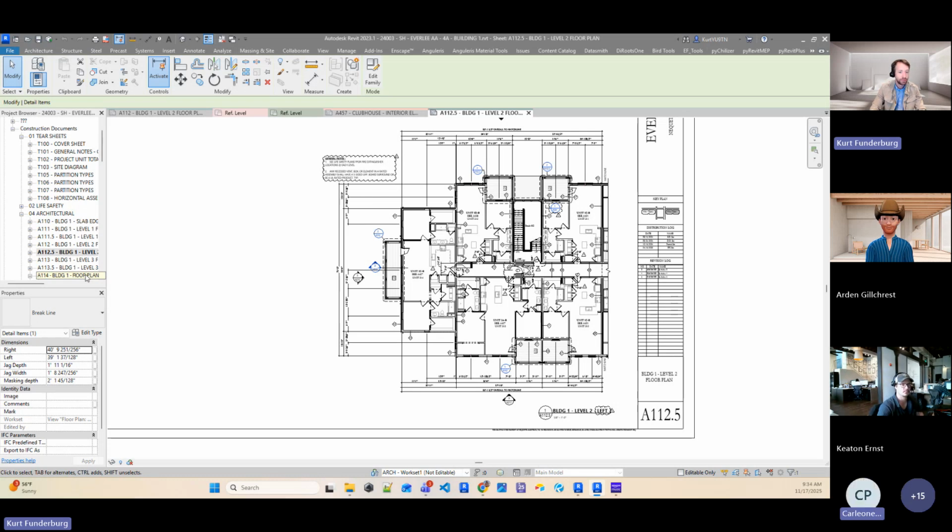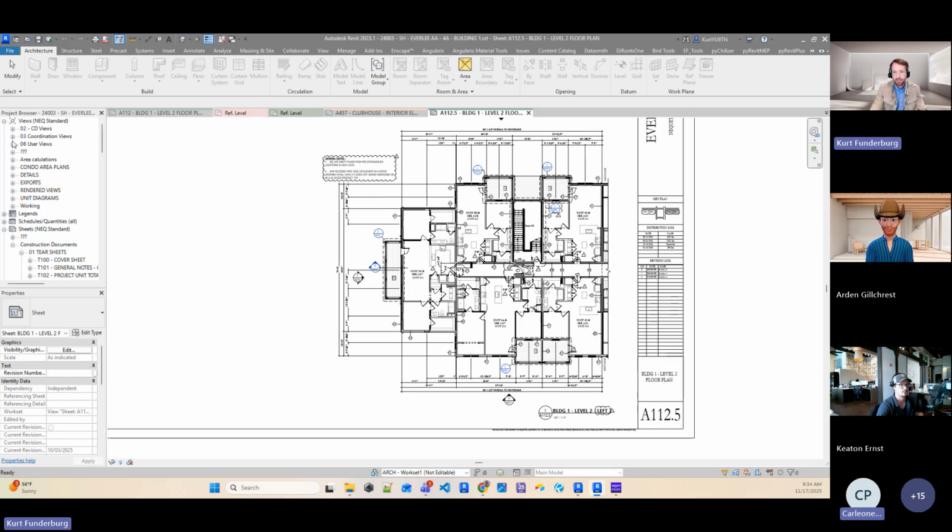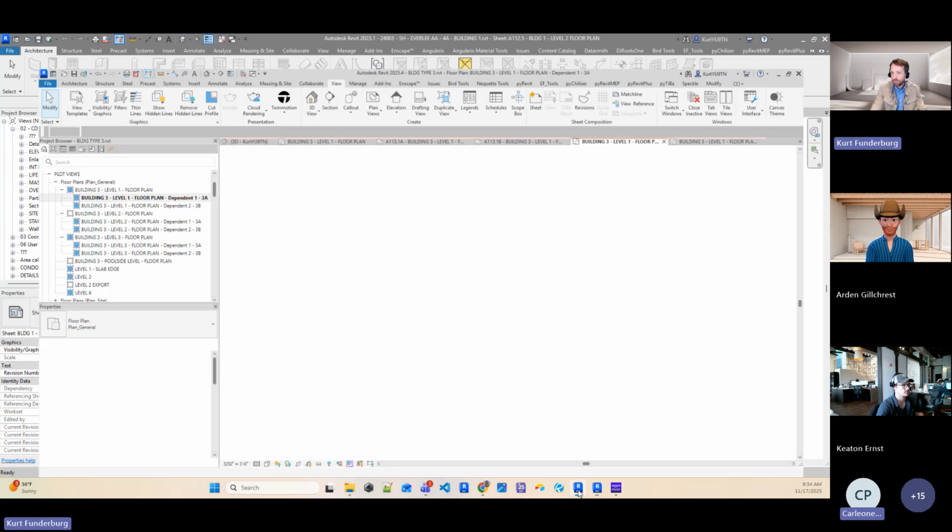I know I sound redundant in some of these, but it just comes from lots and lots of scar tissue. Keep it really simple and try to figure out where your scope boxes need to be, or how you're partitioning your plans, as early as you can in the project. Cartoon out your sets and then make sure that you're talking to your PMs and even your team leads just to make sure the sets are reading correctly.